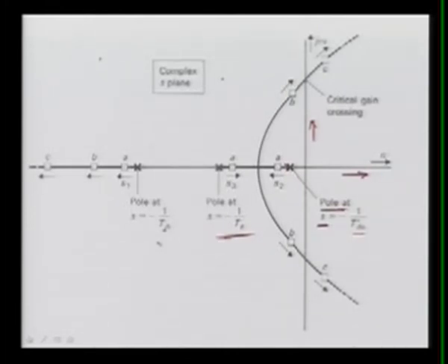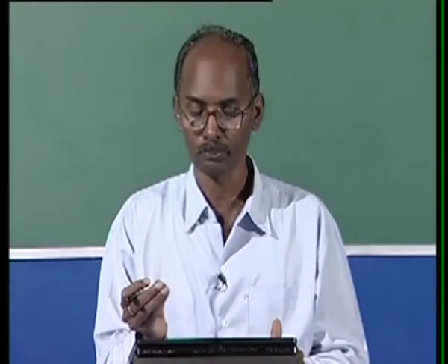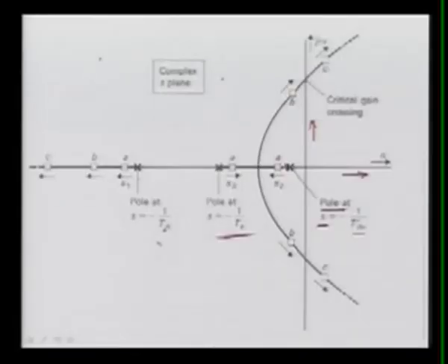Now once the gain is moving, here are these cross points, the gain is equal to 0, that is called open loop gains. Now if you keep on changing your gain, then the movement, as I said, it will go to A point. If you are again increasing the gain, you will reach B point, going in this way and reaching here, and the system is still stable. But again, if you are increasing the gain, let's suppose C point, then from B it can cross the axis here, and then your system, your AVR, will be unstable.